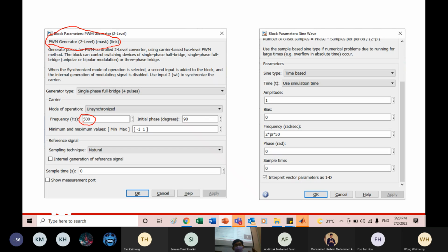So the same concept and theory apply for inverters. Now, the good thing is that frequency is fixed, 50 hertz or 60. So our switching frequency, we can put as long as it is higher than 50. Then, of course, we know that the higher you go, the better resolution you get. But there is a problem: the higher you go, the higher switching loss you get also. So there must be a balance point.